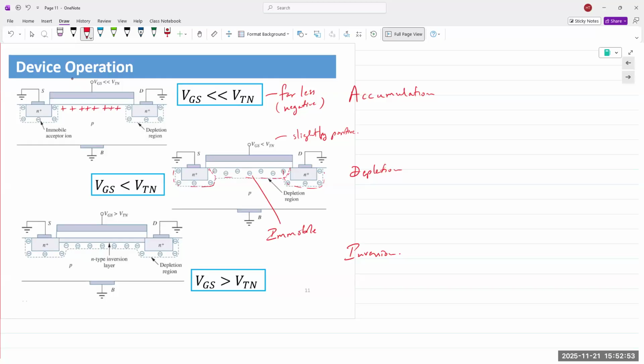They are not free to conduct. So even though the depletion regions have connected from end to end, there's nothing there. But now the gate turns increasingly positive, and it attracts all the electrons up through the junction underneath the gate. Now it forms a shallow layer that connects both n-type regions together, and so now a channel is created between the two.